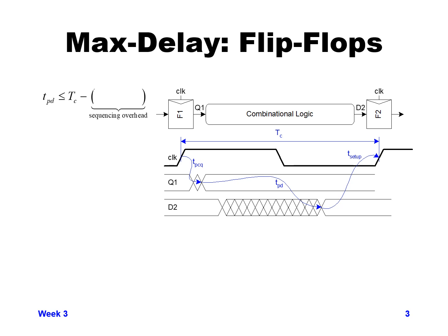So if we take the cycle time and subtract the setup time and the propagation delay time that are totally dependent on the flops, we're left with a propagation delay through the combinational logic, which is the most time that we have available for whatever combinational logic we want to put in there.